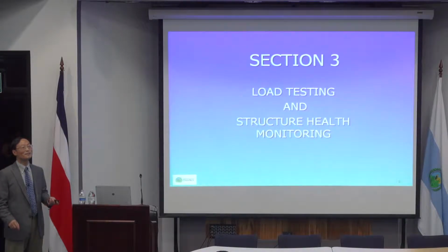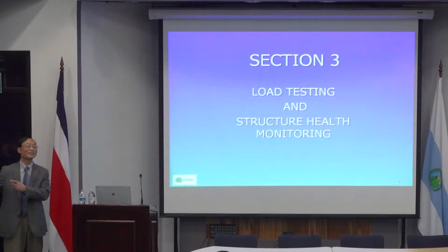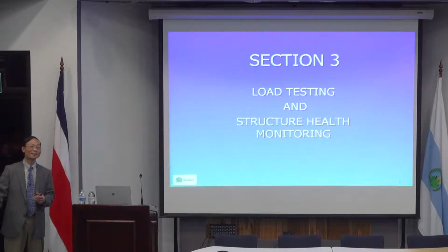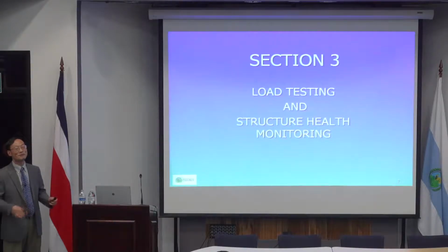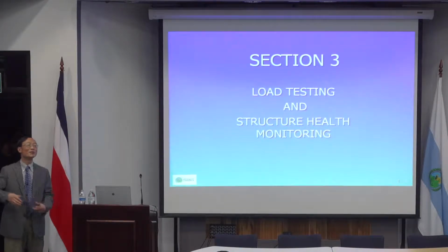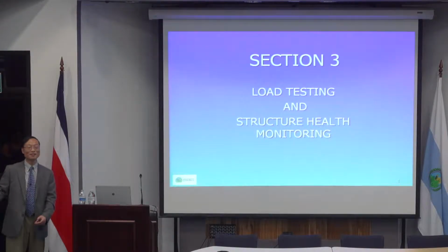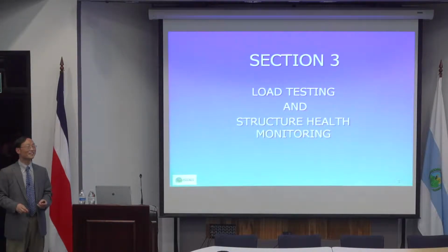So typically when I do evaluation, I don't use that as an argument to significantly increase my capacity. I only use a load test to modify the impact and modify how live load is distributed. But if somebody says, okay, my capacity is also enhanced by load testing, actually, no, I would not be against that idea. It really depends on whether the bridge is old enough and there's no sign of any longitudinal shear failure. I think chances are they'll be fine. They have enough bonding between the deck and the girder.